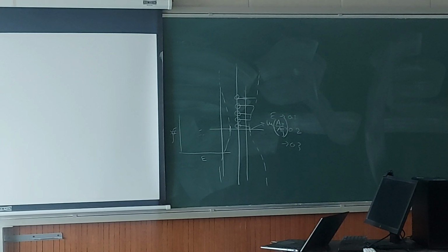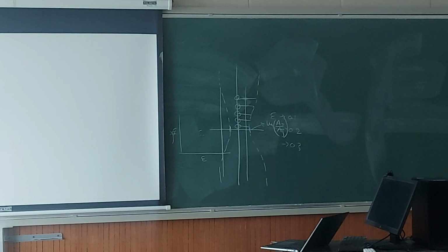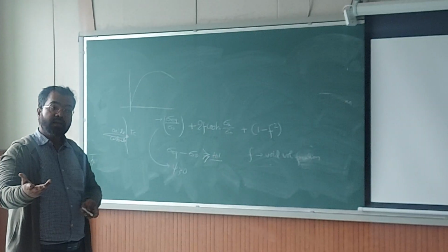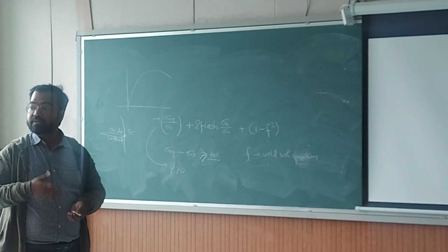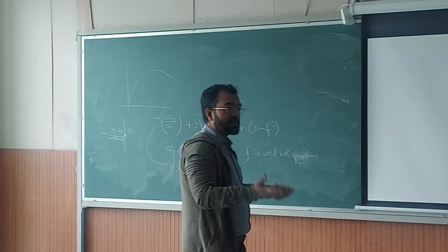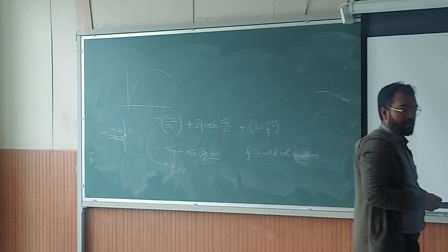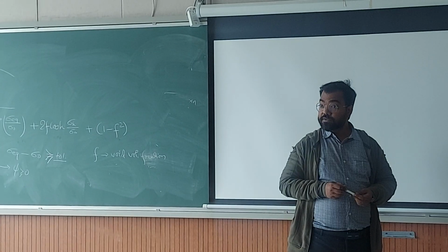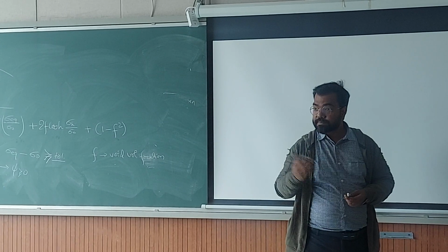The difference will be that if you take 20 specimens, those are 20 different specimens, so all of them have different heterogeneity in them. Different distributions of carbide, different distributions of secondary phase particles, grain boundaries, and other things. One specimen is not going to disturb you that much, but it is also not going to give you that much statistics.